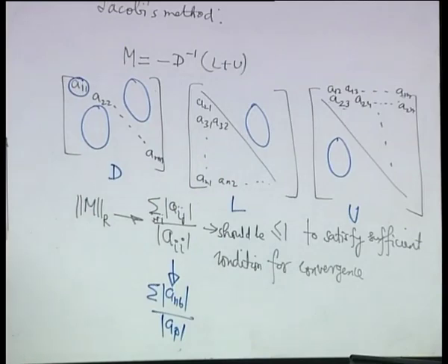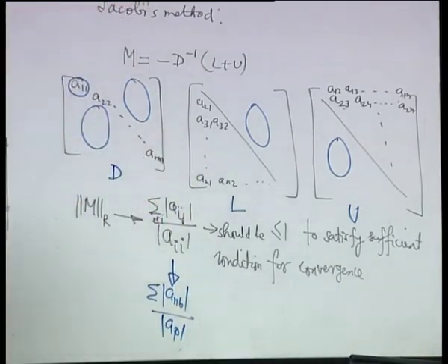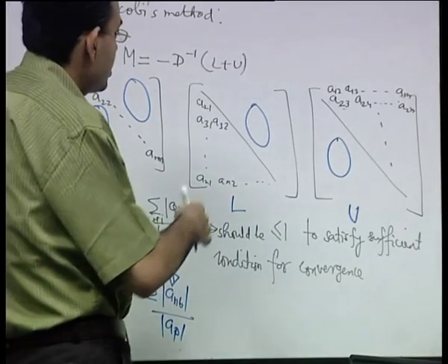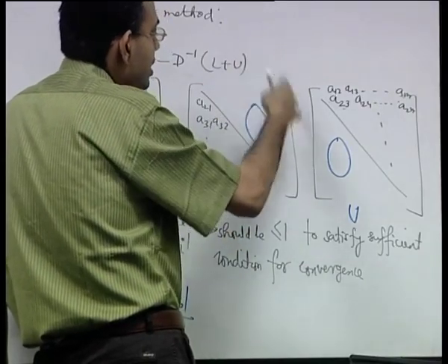For a one dimensional system it is a tridiagonal matrix, whereas for a two dimensional system, considering the finite volume grid layout that we had considered, it is a pentadiagonal matrix. So, you have another 2 diagonals on the 2 sides of it. In the 3 dimensional you have another 2, so 7 total diagonals involved. So, it is possible to have several off diagonal or near diagonal terms, but the matrix is generally sparse.